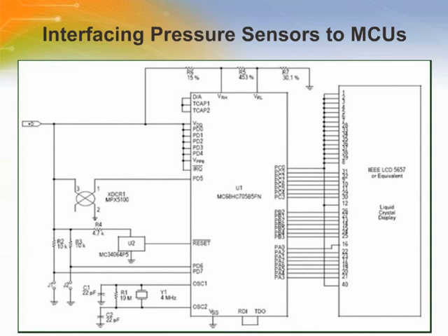Although the total schematic is reasonably complicated, the interface between the sensor and the microcontroller is a single wire. The MPX5100 has an internal amplifier that outputs a 0.5 to 4.5 volt signal that inputs directly to an analog-to-digital port, PD5, on the HC08.